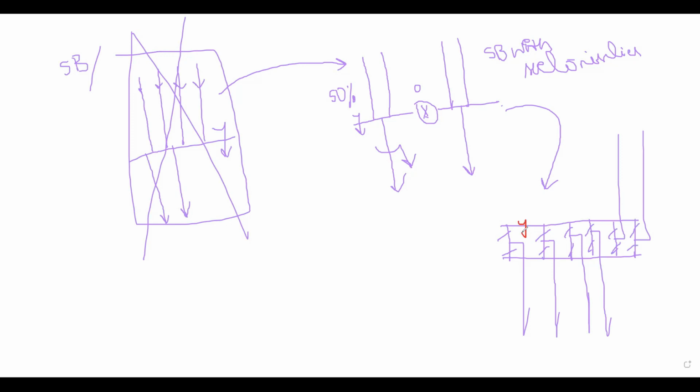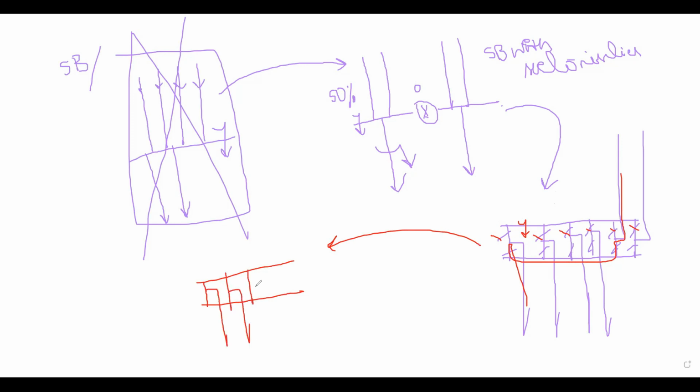Suppose one of the buses fails, then all the power should be shut down, and I will open up the isolators. All these isolators will be opened because isolators cannot be operated in load condition. And I will close all the isolators. Now the power will be pulled through this breaker, through this bus. Some interruption of power is there, but it is more reliable than this. So to avoid that interruption, four incomings, two outgoings.